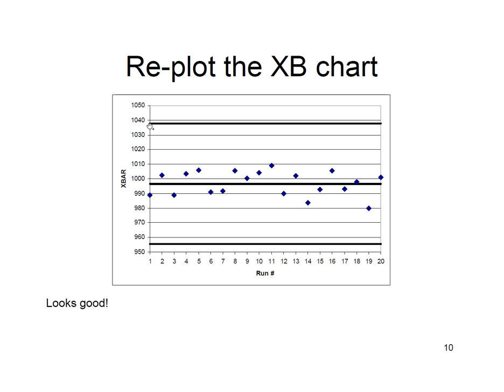And so now we have our upper control limit, lower control limit, and then our mean. And you can see that these are, like here, 1, 2, 3, 4, jumping around the line. 1, 2, 3 going up. 1, 2, no, only 2 in a row going down. So it's actually in control.